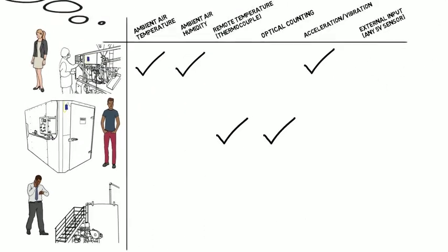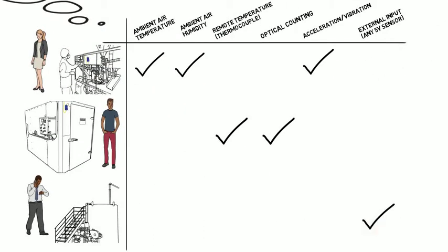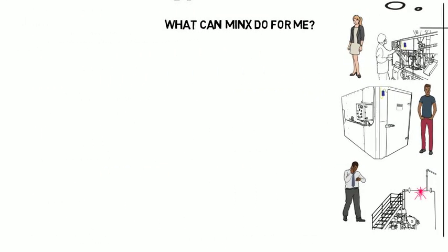So Darnell purchased a simple float switch, installed it on the wall of the tank, and wired it to a MINX 5-volt external sensor input. Darnell also connected an LED light to MINX's external output. Now, no one needs to check the tank each morning. Whenever the tank's water level reaches the float, the LED turns on to inform nearby operators to empty the tank, and Darnell and the supervisor each receive texts. From his desk on the other side of the plant, Darnell can even confirm when the tank has been emptied by consulting MINX's control chart on his web browser.